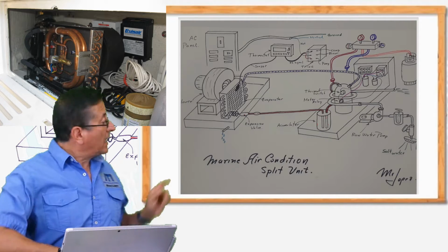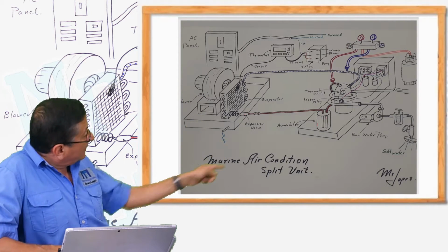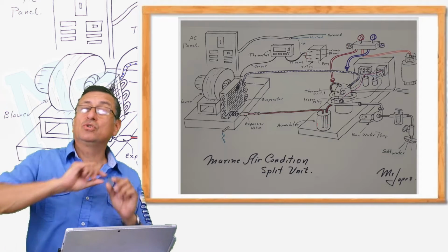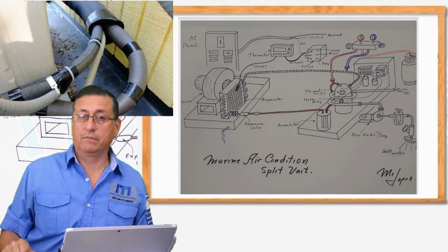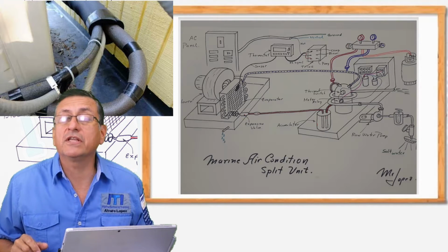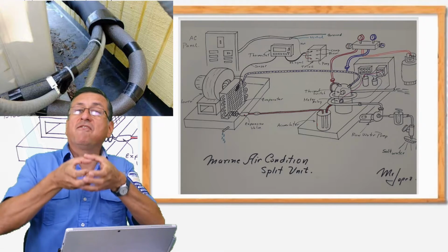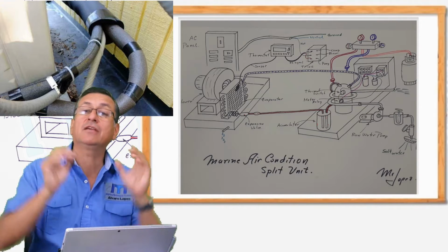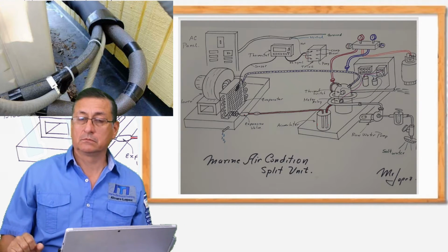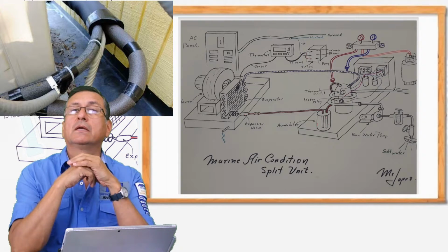But both of them are connected with the blue line and the red line. Those copper lines have a freon, a refrigerant internally. And normally that refrigerant line is covered with a special foam in order to keep the temperature of those pipes isolated from the environment. That's clear?